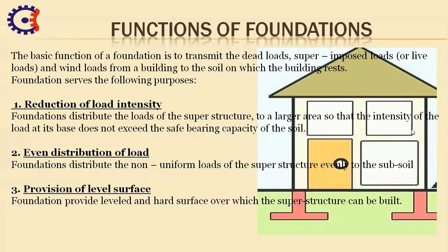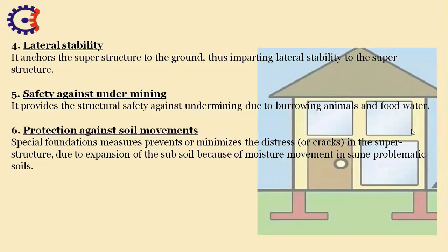Second one is even distribution of load. Foundation distributes the non-uniform loads of the superstructure eventually to the subsoil. The third is provision of level surface. Foundation provides a level and hard surface over which the superstructure can be built up. The next is lateral stability. It anchors the superstructure to the ground, thus imparting lateral stability to the superstructure.